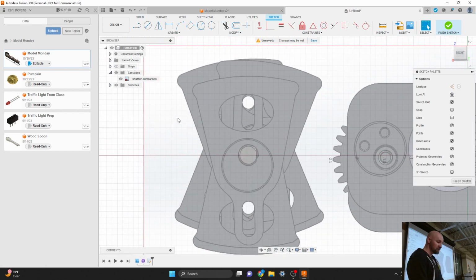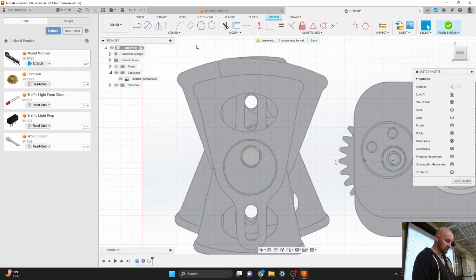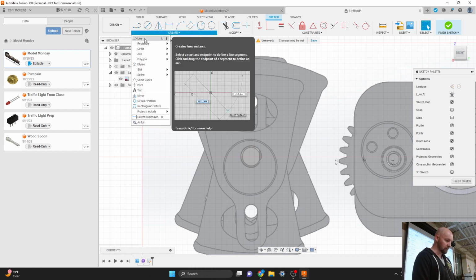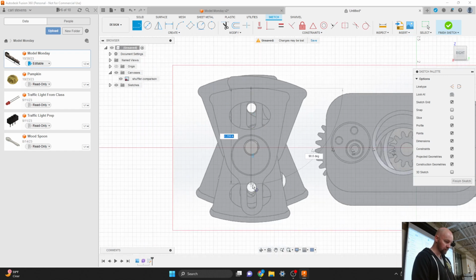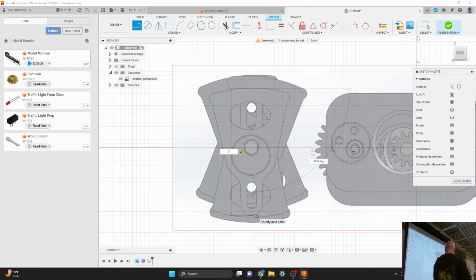And now I'm just going to draw a line. So I'll click on create and then line, and draw a line right down, top to bottom. My line is going to be 3 inches long because that is the scale that I kind of chose. This is how we can turn an imprecise scale into precise measurements, by defining our line distance here very precisely.